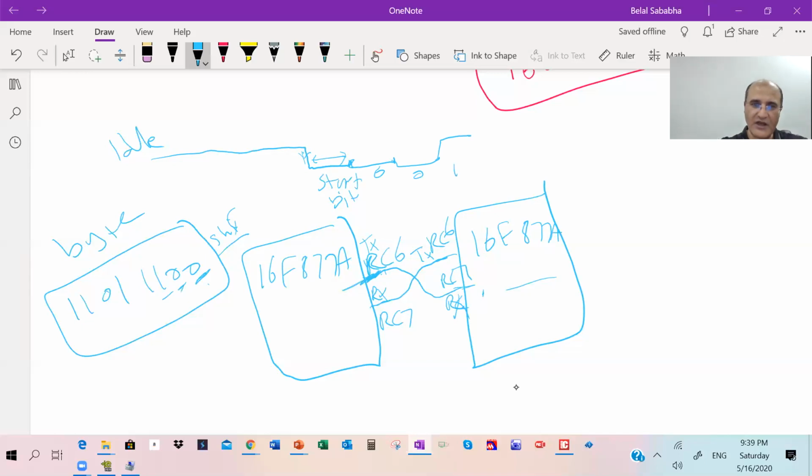And they stay on the line for a certain amount of time that both controllers know. Then you send another 1. Then another 1. Then the 0. Then a 1. Then another 1. Then you stop. You send the stop bit.